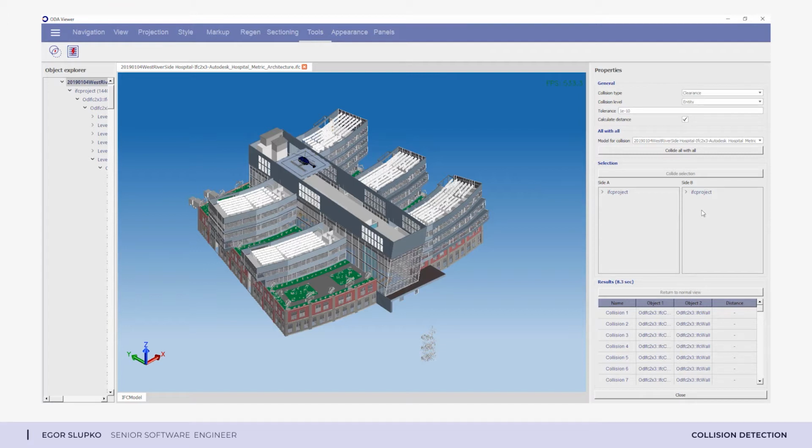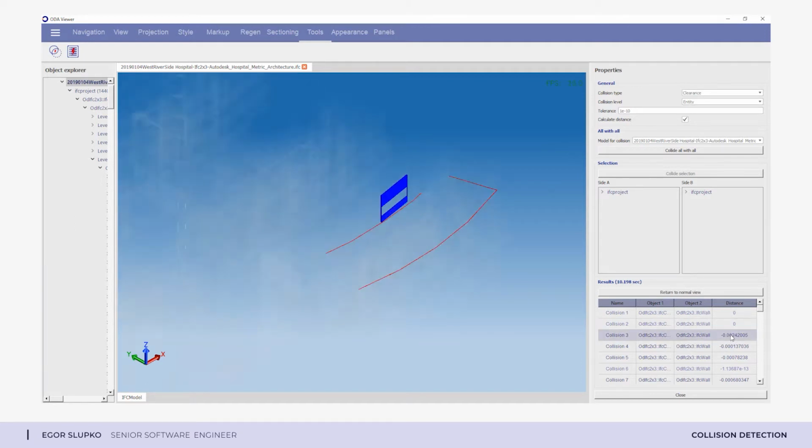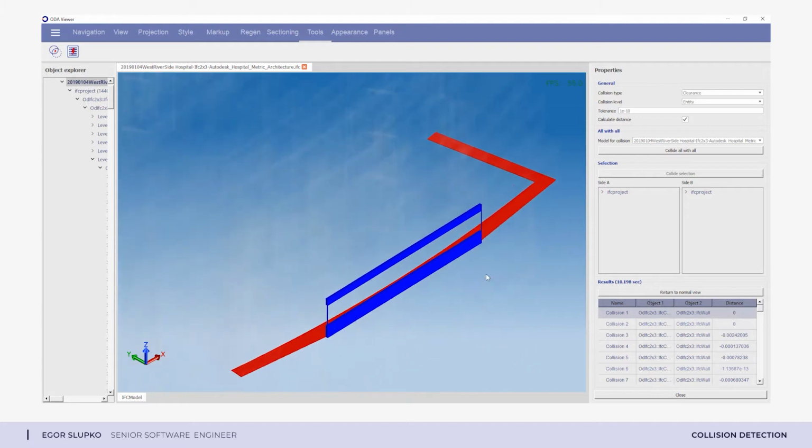When this option is enabled, we have to check all triangles of two objects, because even if we find a collision, another pair of triangles may give greater penetration depth or less clearance value. This mode is more informative because we can always determine the kind of collision: penetration, touching, or clearance. This is all about collision detection, so let's move to the next topic.